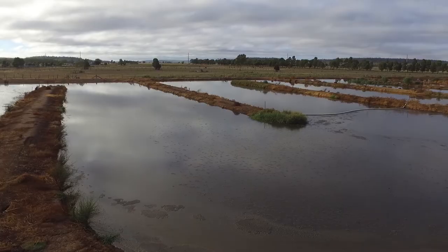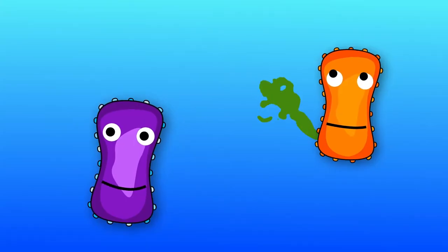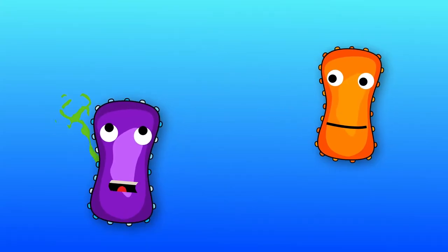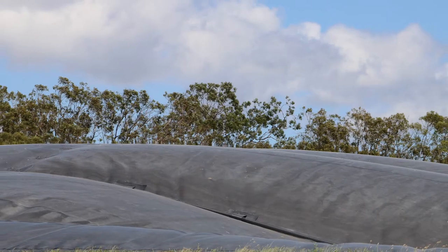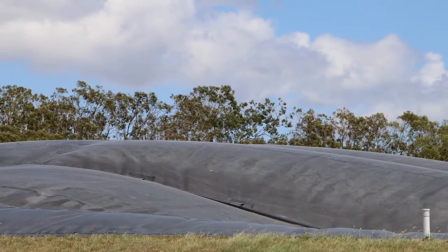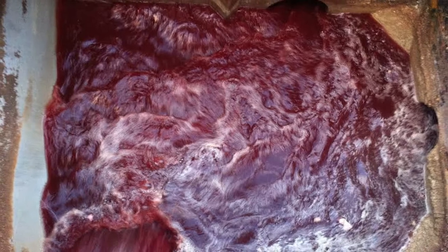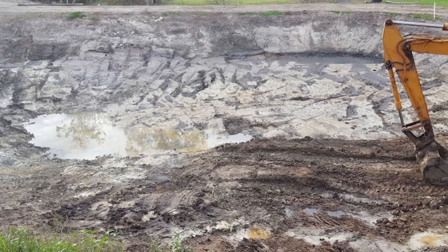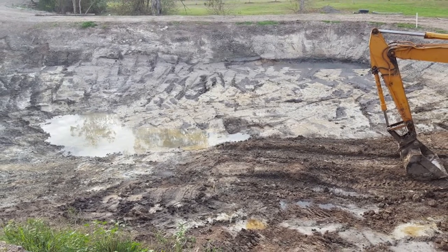If they do, it is usually a sign that either the pond has become anaerobic, typically due to BOD overloading caused by a malfunctioning anaerobic pond upstream, or a severe spill of blood or tallow in the previous month. The pond could also have filled with sludge and desludging is required.